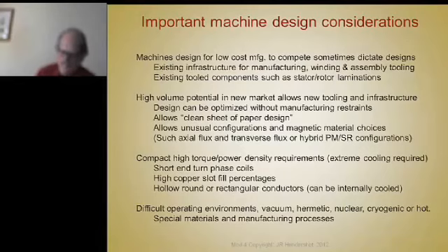That's what reduces the ohmic losses and improves efficiency. The other thing you have to do is have real short end turns. So you wind the coils before you insert them. You wind them very tight, very short, so that the end turns don't stick out very far.